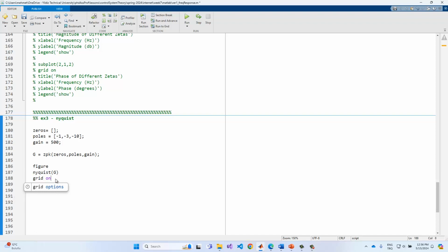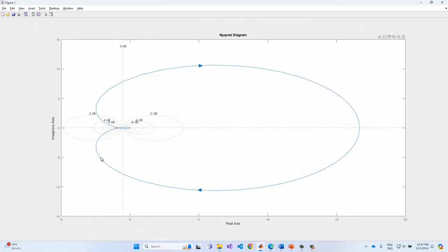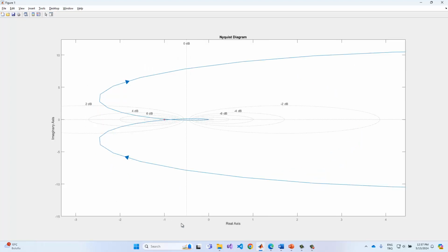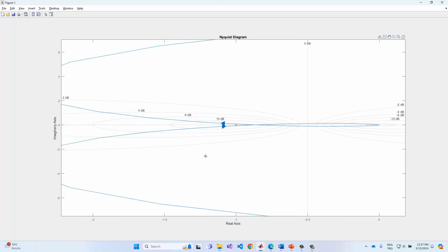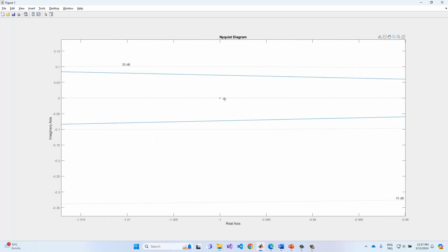Now see that we can draw these lines in here just like this one. We don't have the -1 point in here, and so we don't have any encirclement in here, and so we can check that the open loop and the closed loop systems are stable in here.